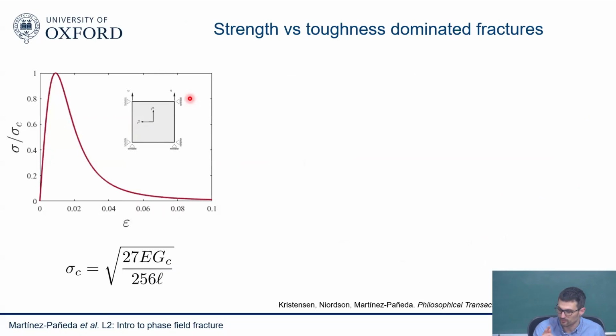At this point, this is a perfect question, because someone could say, okay, you said the advantage of this method versus, I will say, non-local. It's not that different from non-local continuum damage mechanics. It's much better than other computational fracture mechanics methods like XFEM and so on. But the main advantage is this connection with the physics. I don't have 8 parameters to feed that I don't know where they come from. It's just the fracture toughness.